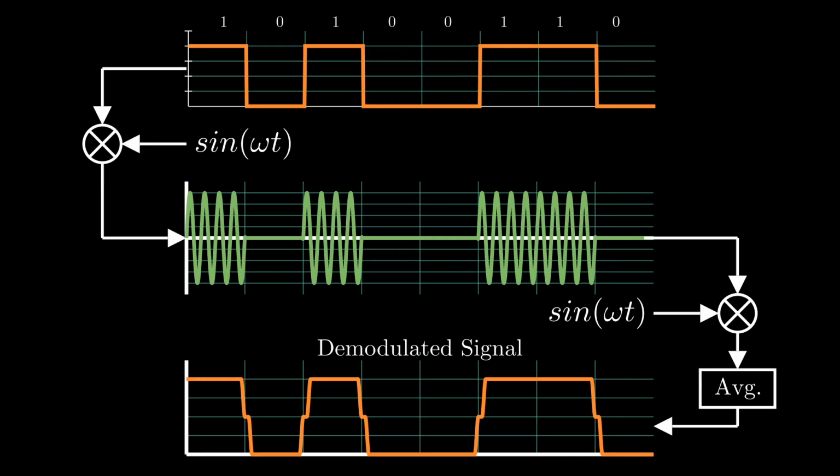And now that we can demodulate our signal, we have all the tools we need to be able to send data across the string, as long as we're okay with being really slow. There's just one problem with this method as we've defined it so far, but that problem will have to be a secret for now, so post your guesses if you want. In the next part, we'll fix that problem, and the solution will put us on the path to quadrature amplitude modulation, which will allow us to send at least 5 bits in a single symbol.